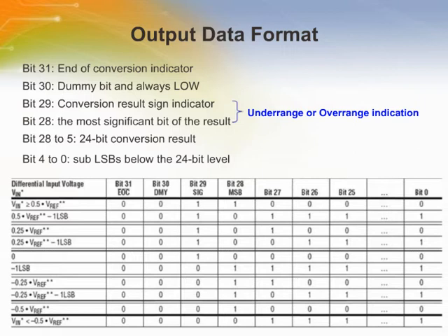without loss of resolution. In the case of ultra-high resolution modes, more than 24 effective bits of performance are possible. Under these conditions, sub-least significant bits are included in the conversion result and represent useful information beyond the 24-bit level. The third and fourth bit together are also used to indicate an under-range condition or an over-range condition.